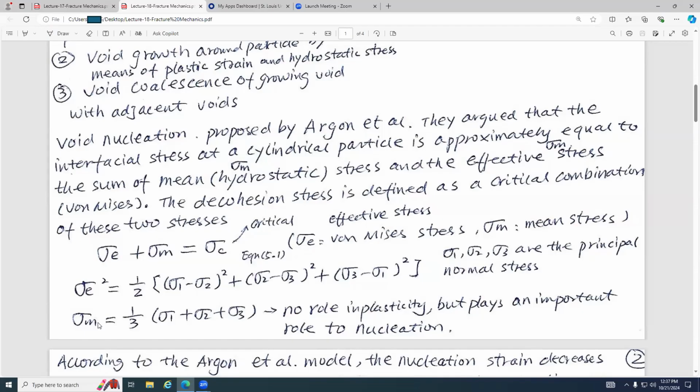What is the principal normal stress? It's like Mohr's circle, where there's absolutely no shear stress. Okay? Mohr's circle, it is on the x horizontal axis. And intuitively it means that on this surface we only have normal stress. Shear stress equals 0. If you have not learned this one, I want you guys to write it down.